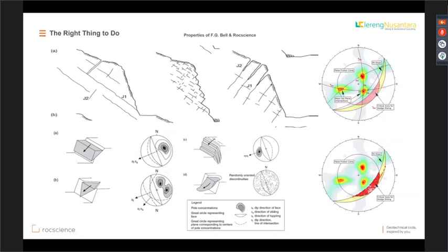And from another perspective, we can also display different features of the critical slip surface, such as the dip of the column base, to interpret the failure mechanism. In this case, validating a portion of the critical slip surface is sliding along the weak subvertical joints defined in the anisotropic model.